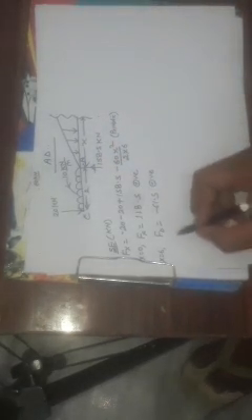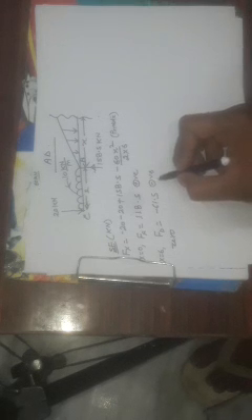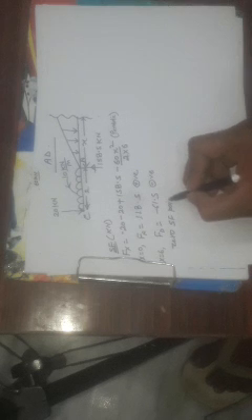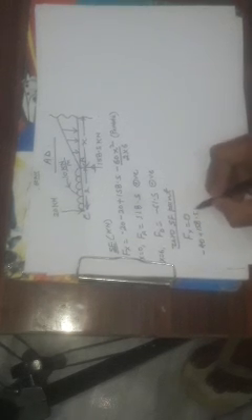So we will calculate the zero shear force point, because the value of shear force at the start point is positive and at the second point is negative, so obviously there will be a zero shear force point. So we will make a calculation for the zero shear force point. For zero shear force point, Fx equal to 0. So make this equation 0: minus 40 plus 158.5 minus 60x square upon 2 into 6 equal to 0.